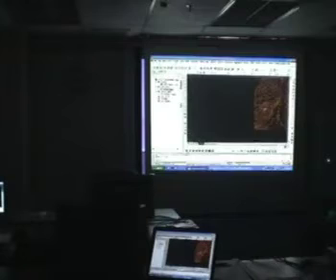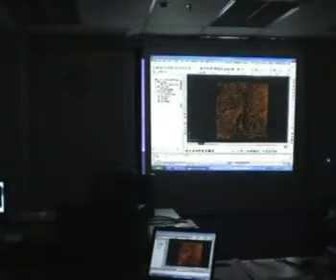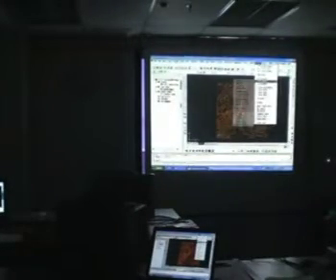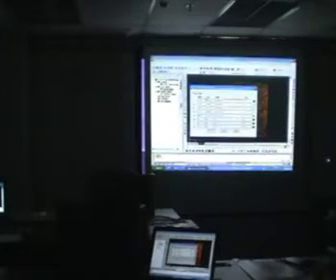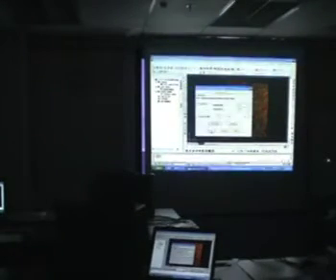Just to give you a bit more about the display, aside from the triangles and the contour lines, there are also many different ways in which you can represent the surface. I'm going to show you one which is quite unique. This is surface elevation shading, meaning I'm going to color the surface based on the elevation ranges. The number of ranges is 5, so I'm going to click auto range. It automatically looks for the lowest and the highest elevation points, in this case from 22 to 77. It divides this into 5 equal ranges for me, and each range is going to be on a different layer with a different color. So the lowest is between 22 to 33, and they'll be colored red, followed by 33 to 44, yellow, and so on. I'm just going to click OK.